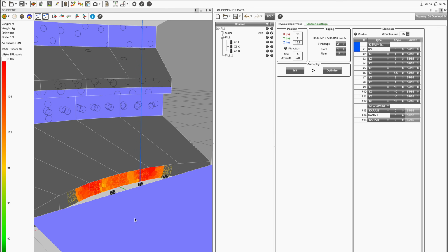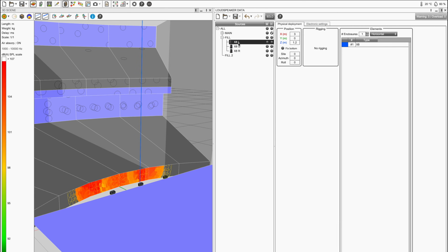To create a parallel link, multi-select sources in the source list by holding Shift on the keyboard whilst making the selection with the mouse. All selected sources must be within the same group, all contain only one enclosure, and all have the same enclosure type. The parallel link will use the settings of the first source the user selects. The unit type on this source must be capable of driving the selected number of enclosures in parallel, else the parallel link option will not be available.